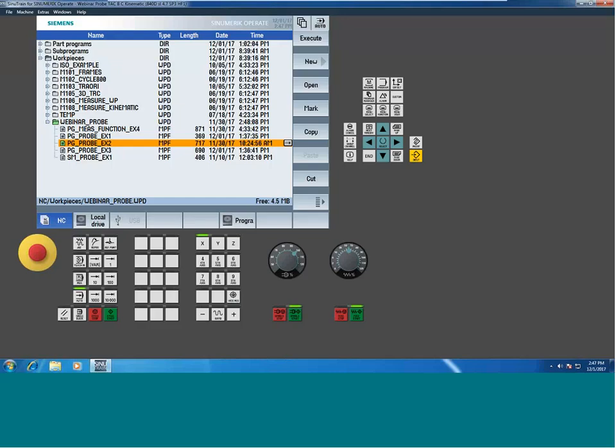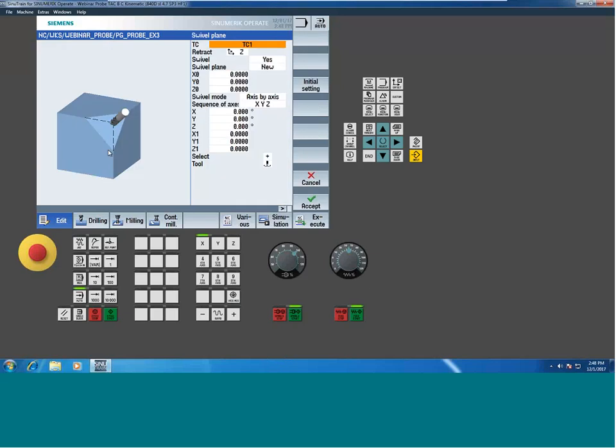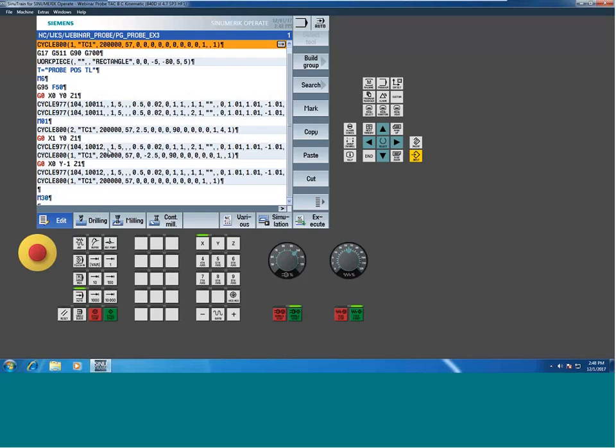So back over to our Sinutrain, example 3 is what allows me to take this measurement. Now in this case, since this is a 5-axis machine, it is mandatory for me to use cycle 800 to move things around. That's how our dynamic fixture offsets work. If you were just positioning this through direct axis moves without using either Traori, which is a 5-axis toolpath, or cycle 800, then what I'm showing you right now would not work. So you do have to drive things. So in this case, my part is sitting with the rotary table sitting at 0, 0.